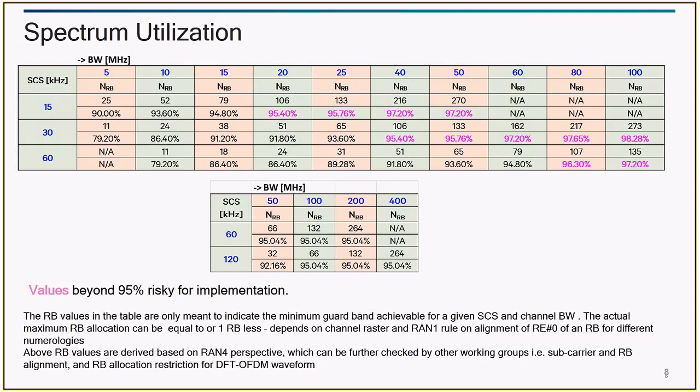At different instances of time. For example, when you move out of LTE and move into NR, LTE assigns you a BWP. It gives you a small area in which you have to monitor. If you miss this, then you have to wait for another 120 milliseconds for this to come back. Otherwise, this is like a grid-like structure actually.